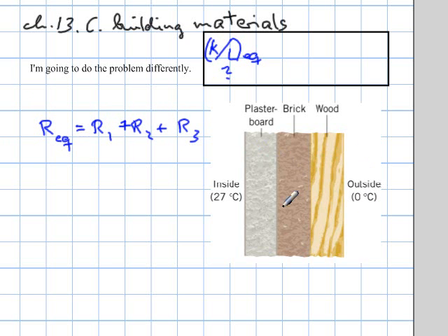The same thing happens with thermal conductivity. After all, heat being conducted sounds almost the same as electricity being conducted. In fact, the equations are the same. So the heat encounters this resistance, and this resistance, the heat flow that is, and therefore we would add the resistances.